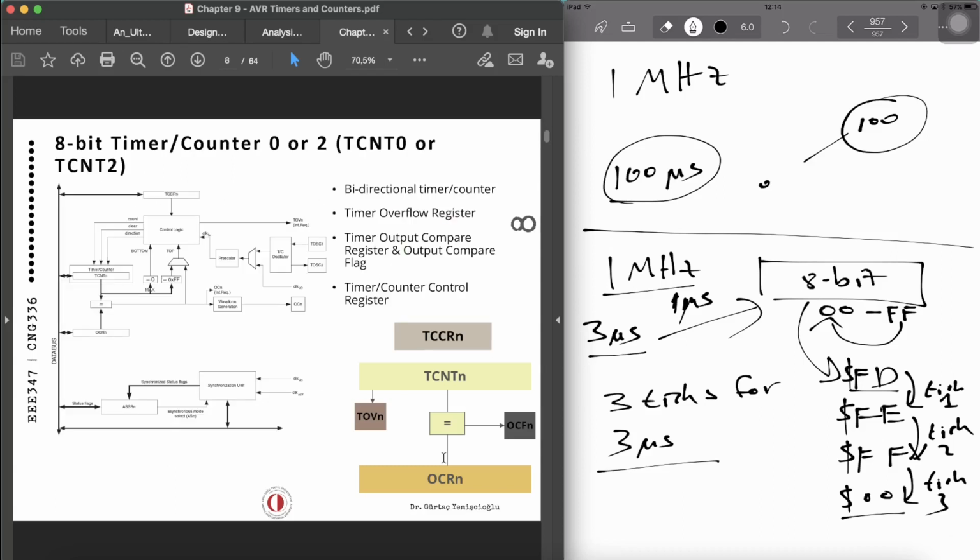As you can see, this is the internal architecture of the AVR responsible for timer counters, and the TCCR, TCNT, and OCRn registers that we are interested in. TCCRn is here, which is the control register. TCNT is over here, and OCRn is here. Of course, we have some other things like the output compare match pins, the oscillators and the prescalers, which we will talk about later on.